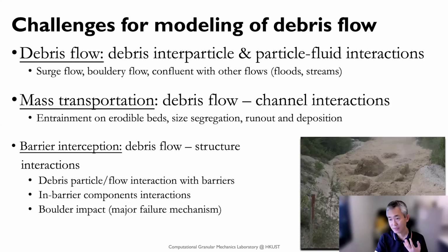And also, if we have a different type of barrier, as we are going to show later, a flexible barrier, then there'll be in-barrier component interactions during this impact of debris flow here. And also importantly, whether any barrier is rigid or flexible, the boulder impact can be a dominant effect that causes damage to this barrier here, right?